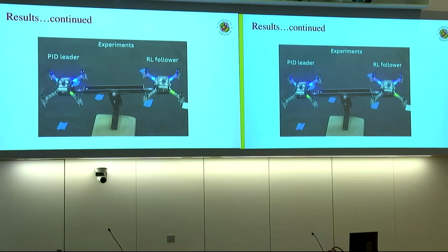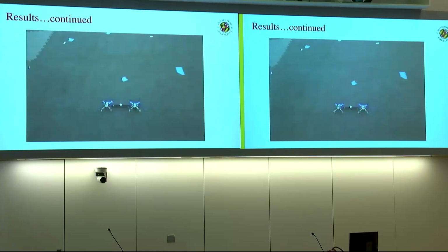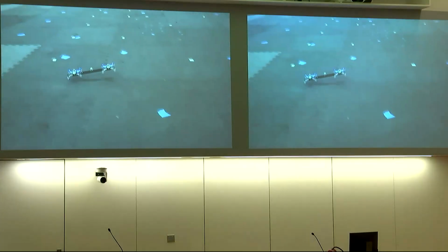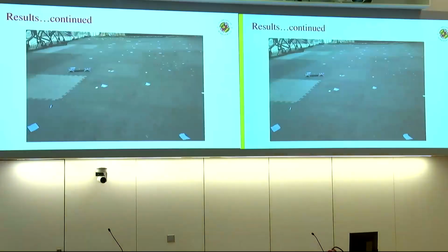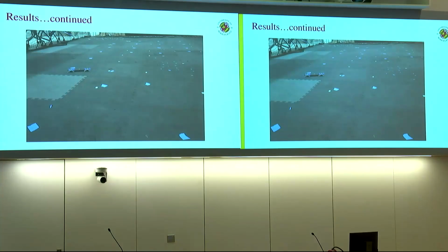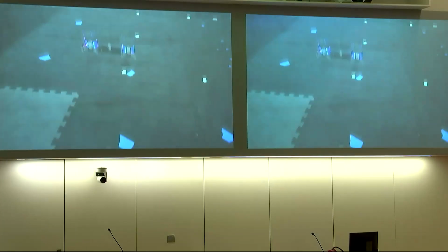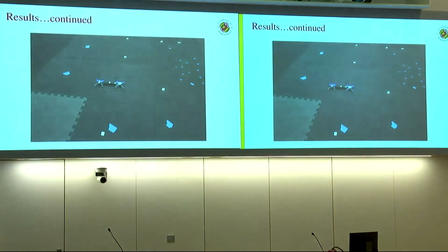But as I indicated before, if the drone tilts, it will start moving. So because of the ball, when the whole system is going to tilt, it will start oscillating. And we won't know whether the ball is getting balanced or whether the system is reaching the waypoint or not. So I tested this in actual flight, and the ball is getting balanced. As you can see the oscillatory motion, though I'm flying it at a lower height just to see the ball, and I'm still working on the tuning aspects. This flies a little higher. The ball remains at the center, or is trying to remain at the center.